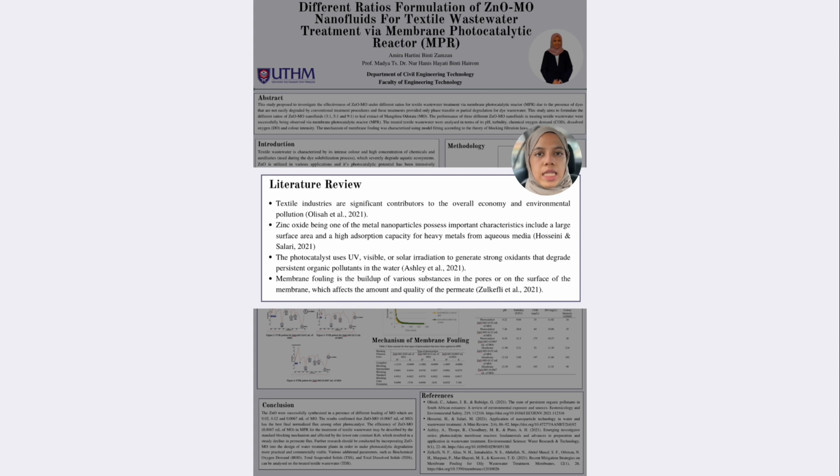Fouling of membranes is typically characterized depending on the type of foulant or location of the fouling. Foulants fall within the categories of particulate, organic, inorganic, and biological microorganisms. Fouling can happen either internally or on the membrane surface. 4 fouling methods exist in a broad sense, which are complete blockage, intermediate blocking, standard blocking, and cake formation.